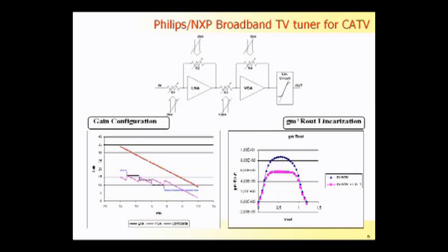This is a representation of the simulation of the principle of behavior of this linearization circuit. We can, in first approximation, assume that the voltage gain of an inverter, which is the core of the amplifier, is equal to the product between the transconductance, gm, and the output resistance, R out. So we can linearize either R out or gm. The way to linearize gm is usually a narrowband solution. It is not possible to apply it in this case because this amplifier has to present a wide band around 1 GHz. So I decided to design a circuit able to linearize R out.